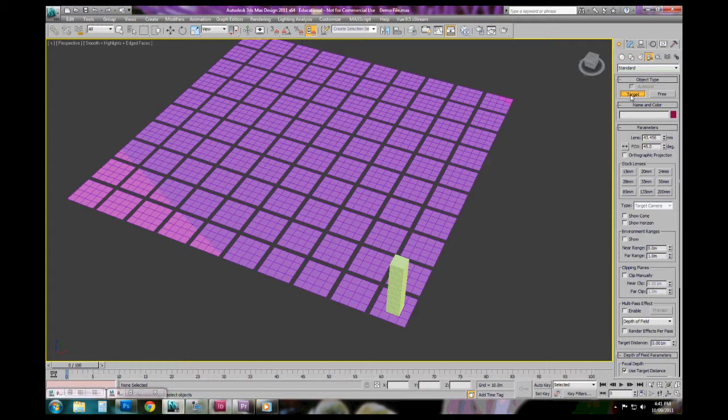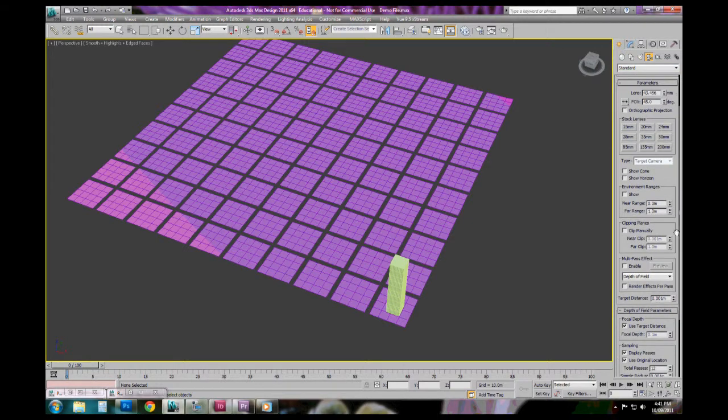So we select target under camera, it's highlighted, and we can actually set the parameters for this camera straight away, but what I think we should do is just drag it out in the view. So what I do here to create, I've clicked and I'm holding down my mouse button, and I drag out the little target icon, which is that little cube on the end of my cursor, and I put that where I want to look.